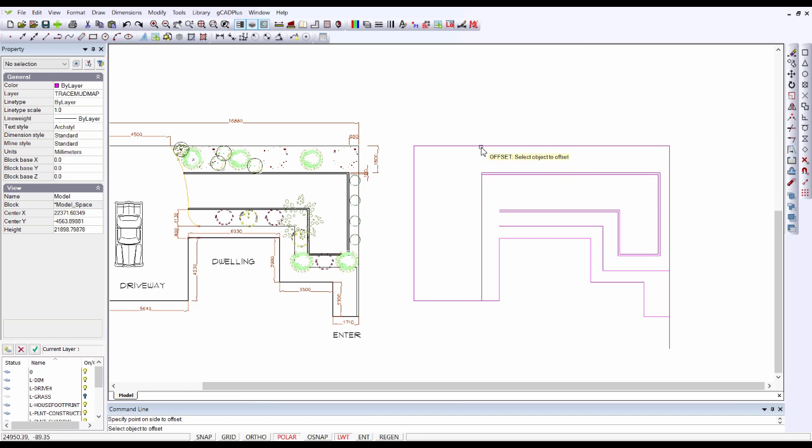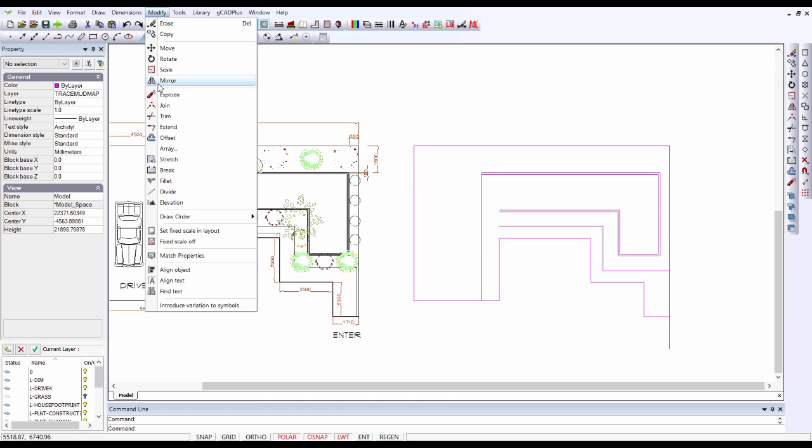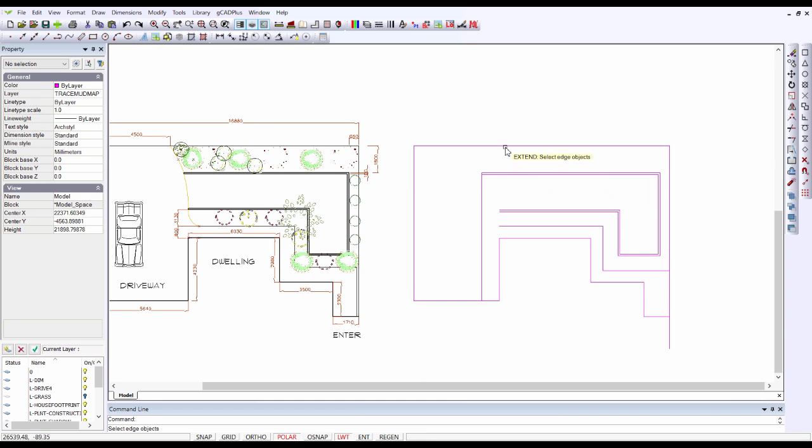We do need that point there, so that trim, let's exit from there. We have to go back and extend. We're going to extend this line to that boundary, so there's the boundary, and extend through to there. We do need that 4500 offset because we're going to throw an arc through here and then bend around. So you can see the offset command in combination with trim and extend works really well. We now have a garden bed area running through there, and our path. Our final step is just to put the arcs in to define the boundary of the driveway.